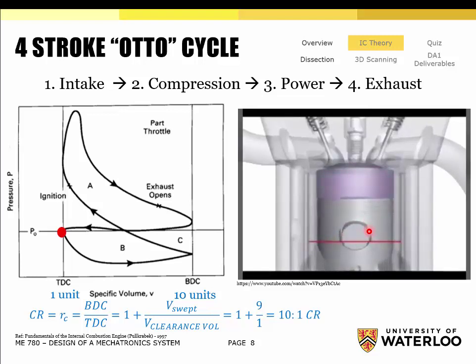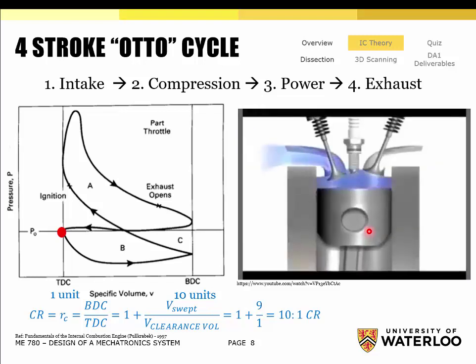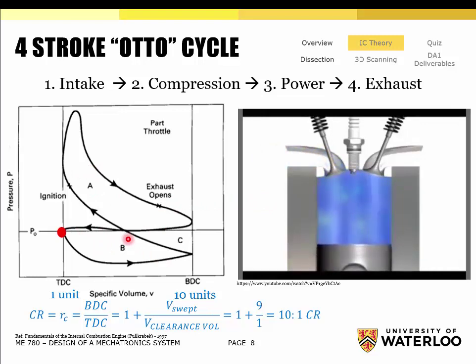So when we have force, which is pressure, times distance, which is volume here, when you divide them both by the bore size, that's what you get. It's just force times distance. So the area inside this is your positive work in this upper loop here. And then the area underneath is your negative work or your pumping work, because that's not doing anything useful. Okay? Does anyone have any questions regarding that? We'll talk a little bit more detail about this in a second.